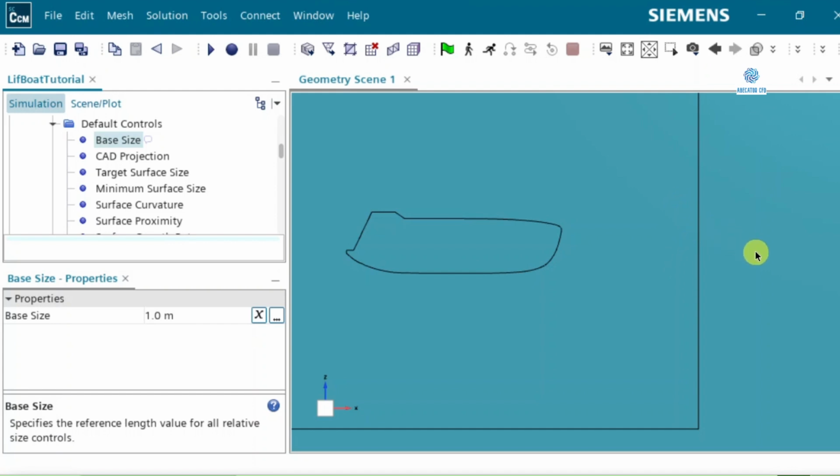Then, when I move into the background mesh, we already set that region to 1.25 meters. So the change in cell size between overset and background is only by a factor of 1.25. That is a very reasonable ratio for increasing cell size. That is exactly what I meant by a smooth transition between cells.